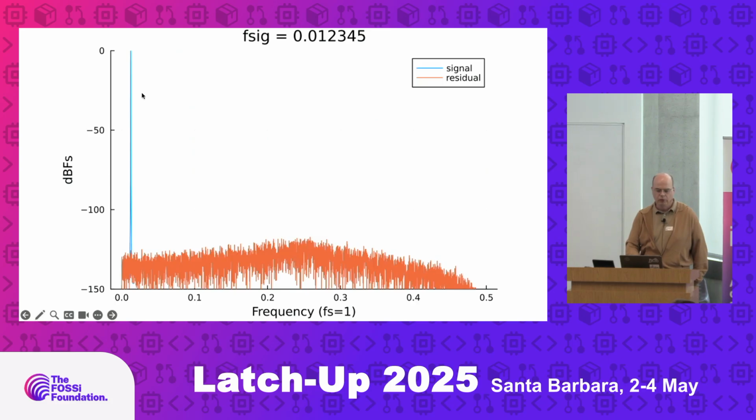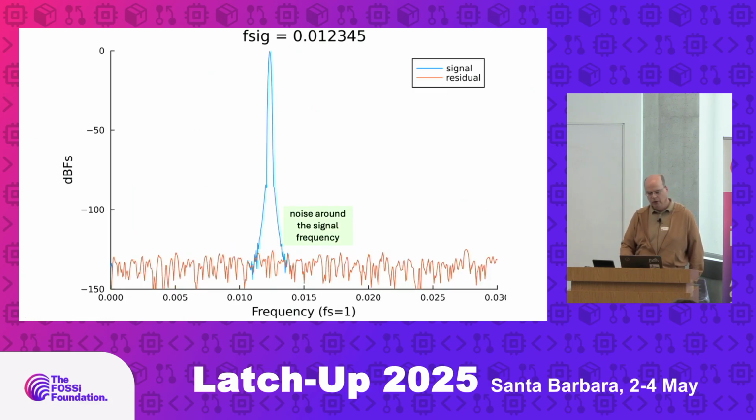This is probably more what you were expecting to see, where you have the input signal, a nice perfect sine wave, and a noise floor. The noise floor has a shape to it, and we can measure how much noise there is, work out signal to noise ratio and all that kind of stuff. We can zoom in here, and I find this is just absolutely amazing. This is the mathematics of linear algebra. The FFT of the output of the filter is an impulse basically.